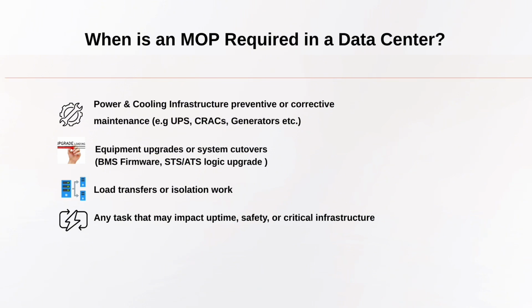Next, MOPs are mandatory during equipment upgrades or cutovers. That includes uploading new firmware to the building management system, updating the logic on STS or ATS units, migrating to a new monitoring platform, or replacing control boards inside a UPS. Any change in configuration can introduce new risks if not carefully managed.